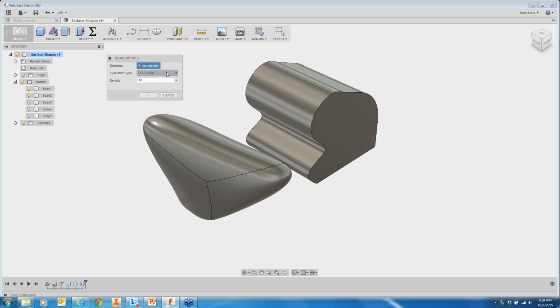And when we talk about the space in a surface space, rather than X and Y, it's usually referred to as U and V. So I have a U direction in one and then V in the other direction. I can find out the minimum U value and maximum U value, and then minimum and maximum V values for that surface. So that's what this program is doing.